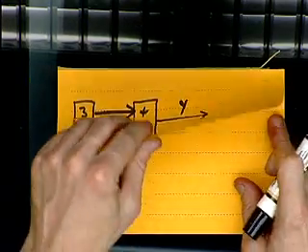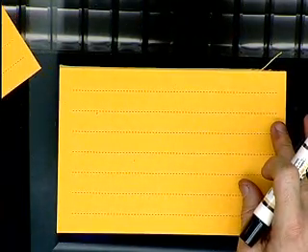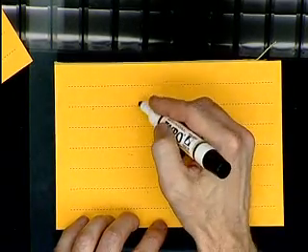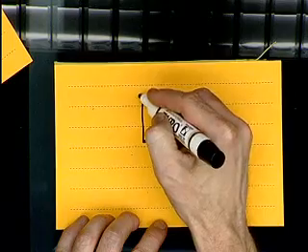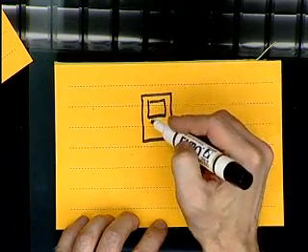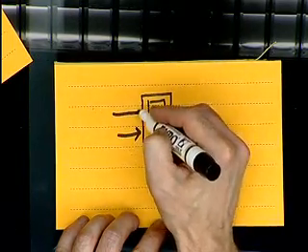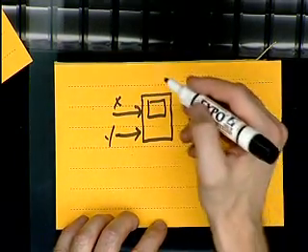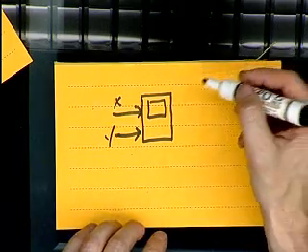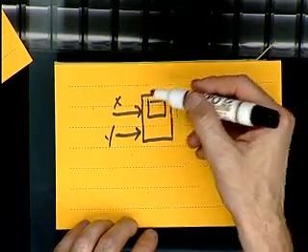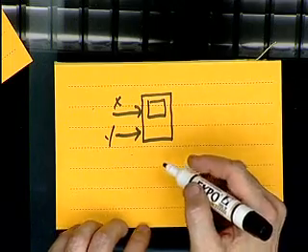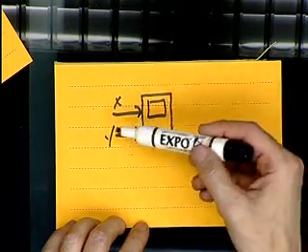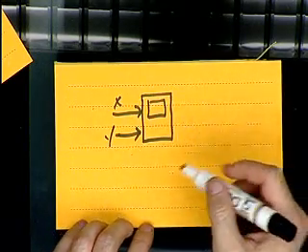And the other block I'll show you right up front is there's actually a variety of output blocks. I'll show you a couple of them. There's an XY plot that takes 2 inputs, x and y, and then you can double click on this plot to make it graph. x is the independent variable, y is the dependent variable, so it's y versus x that it would graph.